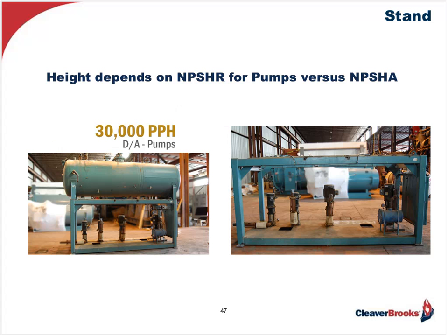Getting back now to our 200 horsepower boiler example and the information we have deciphered about our respective requirements, we can now select the stand for the DA, which also serves as the platform for my pumps, as you can see. We said before that our boiler will evaporate 831 gallons of water per hour, and we want 10 minutes of storage, or let's say we want to hold at least 150 gallons. And with this information, the tank is selected.